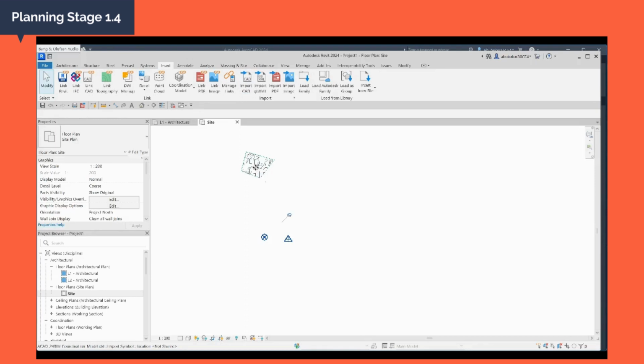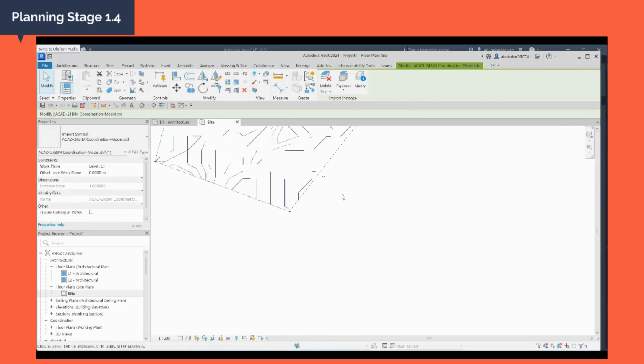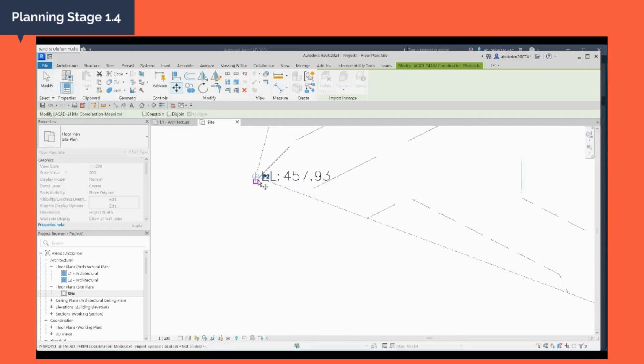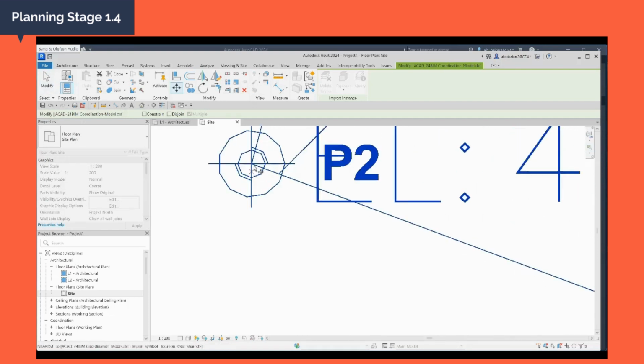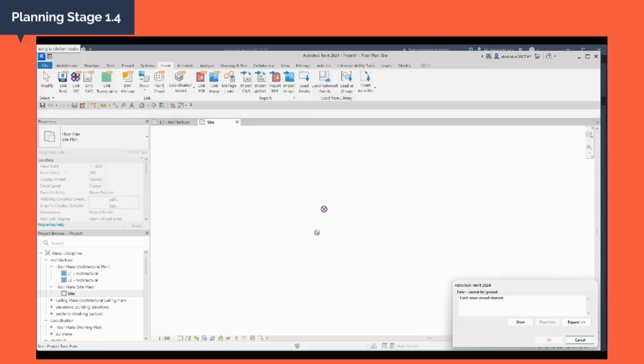So a means of controlling this site is, you can see the control point. You need to move this point to the precise location, which you use as a reference. Remember, we use our reference, our coordinates, this point. Then we check it down to the coordinate that we picked from Civil 3D. You can see this is the point. So then you move it.